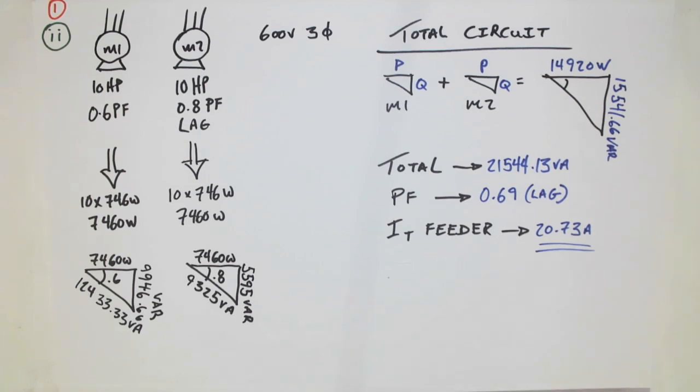Now, this situation here is not one that you would run into all the time. Perhaps they're just using the synchronous motor not to power factor correct, but instead to simply stay synchronized with another motor elsewhere in the process. Either way, seems like a bit of a waste when you could run it at unity.